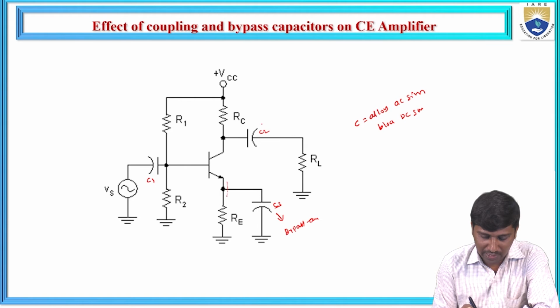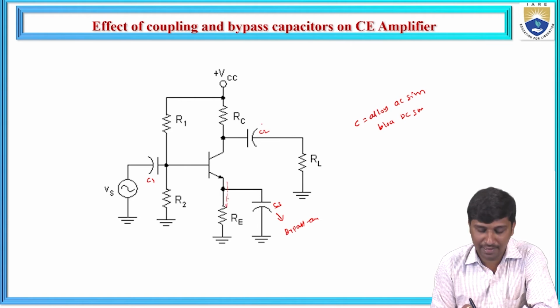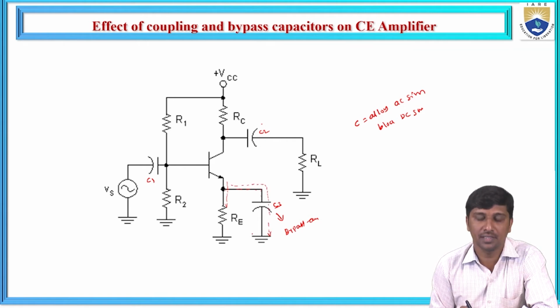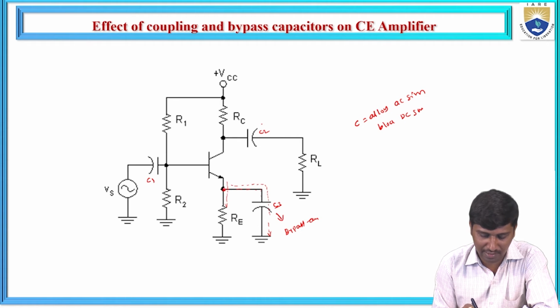While passing the DC signal, if it contains any AC harmonics, those AC harmonics pass through this capacitor. For these AC harmonics, the capacitor acts as a short circuit. Hence, whatever noise is there in the AC ripple is taken to ground potential, and a complete DC signal is leaving at this point.